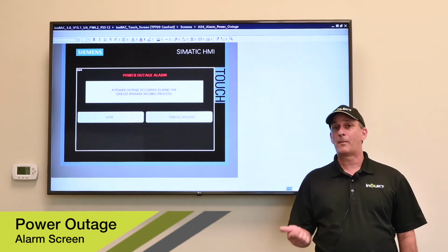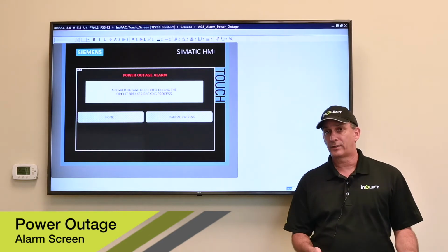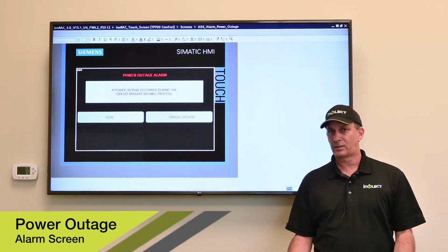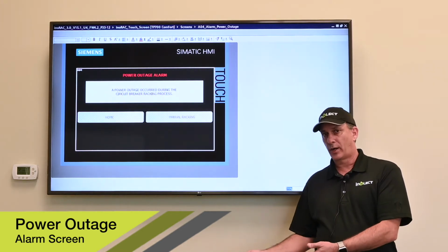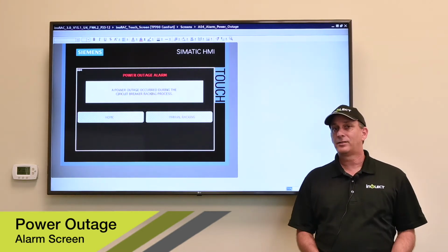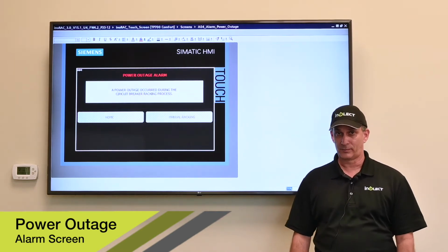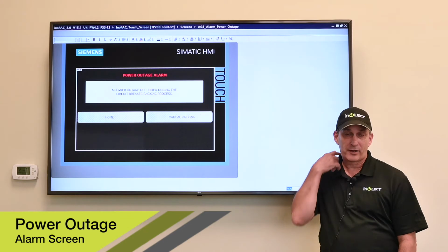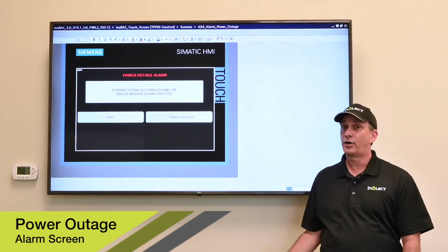And it's just a reminder that during the last racking sequence, power was interrupted to the system, and that's so you can check and make sure that the breaker you're getting ready to rack is indeed finished racking to the connect or disconnect position. So even though this is not a very common alarm screen that you're likely to see, it's a very important one.